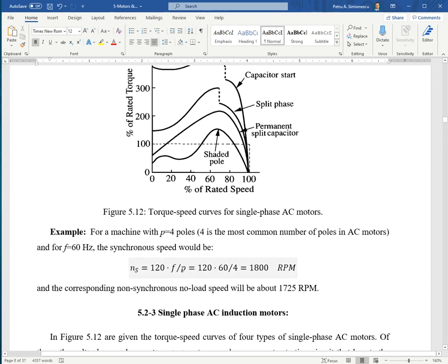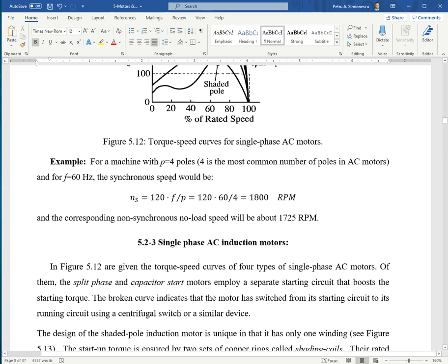Simple sample problem. So for 4 poles, 60 hertz, the nominal RPM for a synchronous machine is 1800, with slip not considered. Sometimes values like this one, maybe let me change this because it's a very common nameplate characteristic of asynchronous motors. So it's less, 1750.